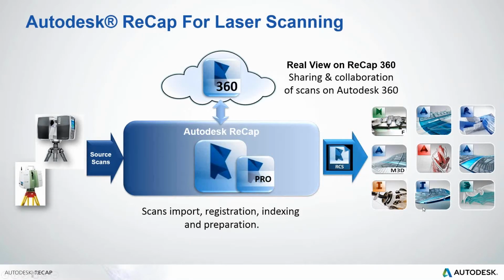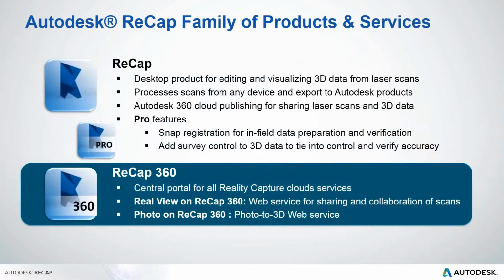How this works is you take your laser scans and bring them into ReCap, and then from there you can collate, organize, turn things on and off, and clean them up, so that you can use them in just about any of the tools in the design suites, whether that's InfraWorks, Revit, AutoCAD, or Navisworks. You also have the ability to upload your scans into the cloud, onto Autodesk 360. This allows the sharing and working on of these with anybody, anywhere, as long as they have a web browser.